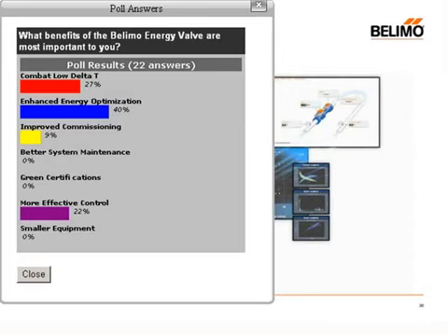Basically, the cooling power of the coil is always going to be above the cooling load that the zone is seeing. If, for whatever reason, the zone is seeing a higher demand than the air handler can actually produce, it doesn't matter whether we're imposing the delta T or not. The coil will not be able to supply that zone.